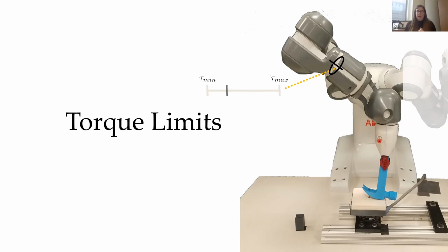So how do we quantify how much these particular joints can take? What we need to do is transform the wrench experienced during our task into the torque experienced at our joint. To do this, we use a mathematical operator called the Manipulator Jacobian. There's a brief review.